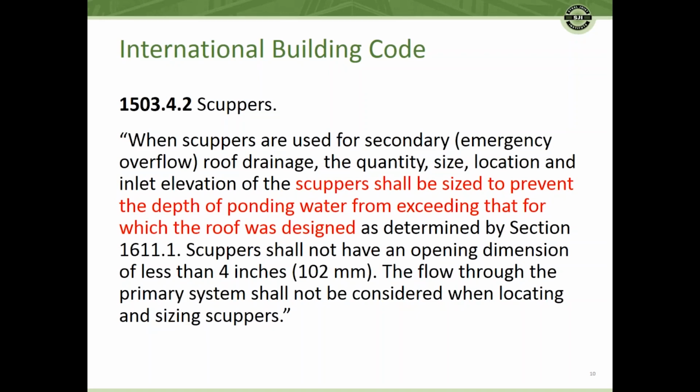Most architects would say if they want to look at the side of your building, they hate to see the little openings in it that may have scuppers in a precast or a tilt-up wall. But my viewpoint is that they should be as big as they can be, because that is what's going to let the water off the roof. So anyway, that's a minimum size.